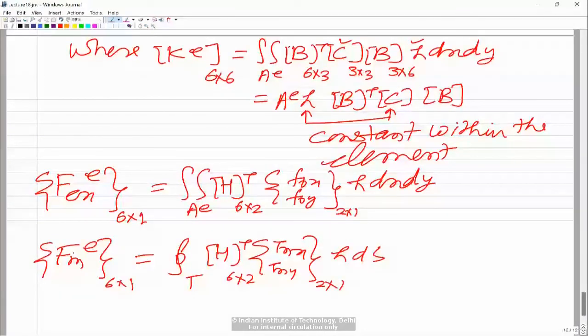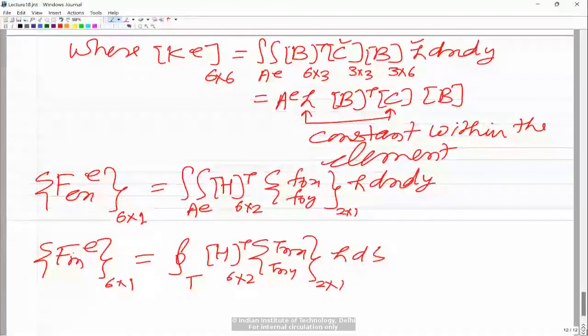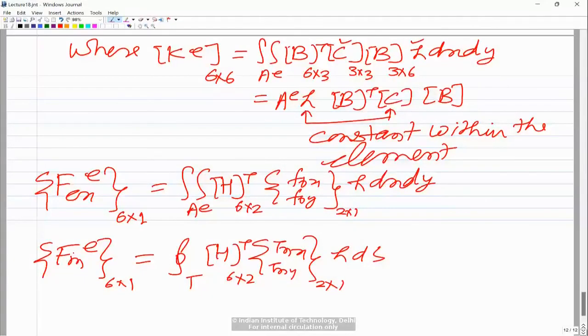Now, as I was talking about, if you have a support in a pipeline in a ship or a submarine, you will have piping. I think you would have seen that. There are many pipelines, and the pipelines are supported at some intervals. For those supports, if the cross-sectional dimensions are comparable to length, at least in one dimension, then you can model them using this plane stress plane strain element, because the loading is in the major dimensions, in the plane of major dimensions. So they can ideally be modeled as a plane stress plane strain problem, such as a bracket for supporting a piping.